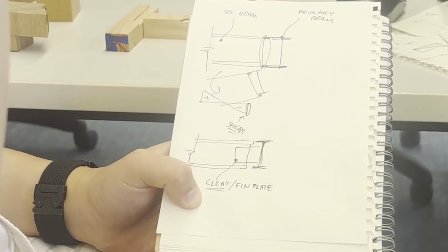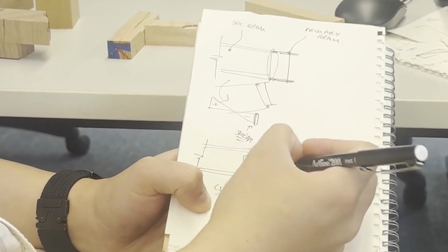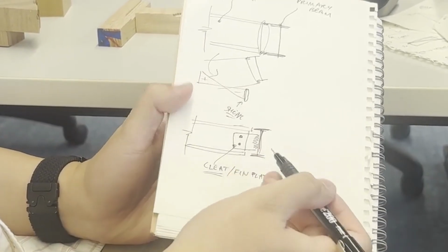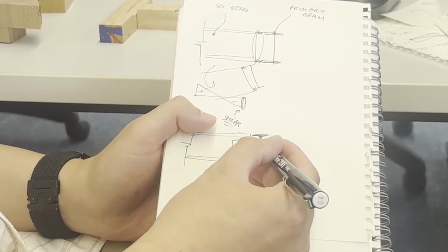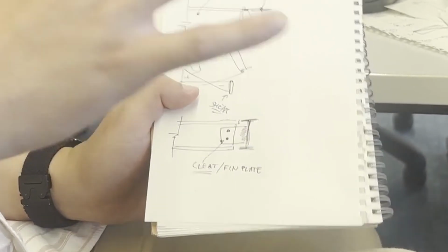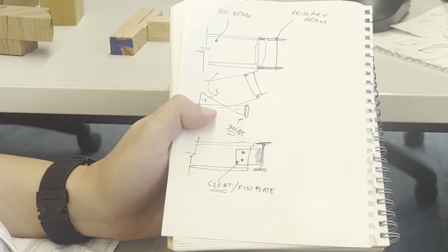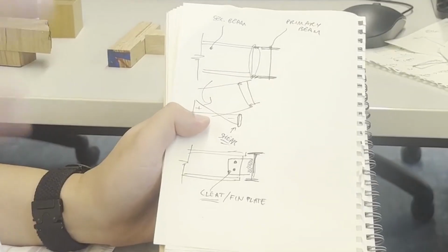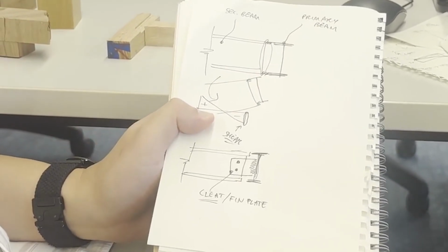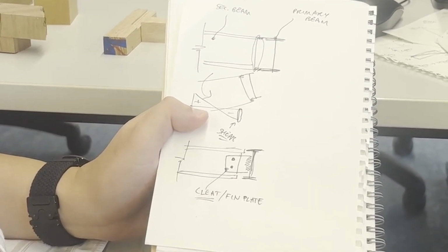But it's a cleat basically. And it's a pretty clever idea in general with plates and connections to weld one side and bolt the other side. The idea is, when it comes off the truck, this little cleat is not going to mess with fabrication. On-site fabrication of steel is very much like these steel fixer tradies assembling Lego, basically. The pieces just have to easily come together, and you don't want them to weld, because welding is very hard, and it requires certificates and stuff.